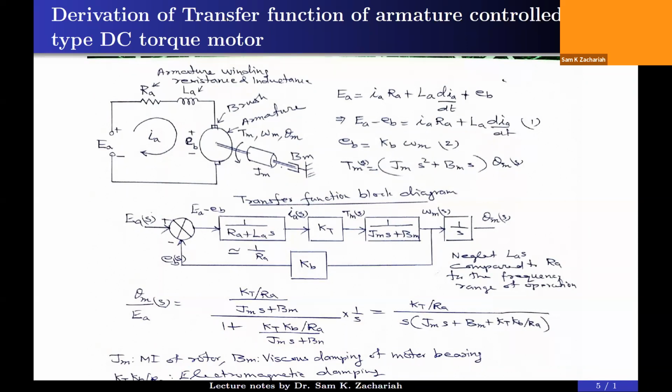But while you are riding, if the dynamo is generating voltage and the voltage is connected to the front bulb, and the bulb is producing energy in terms of heat and light, then there is a finite resistance for the circuit, and whatever additional effort you apply on the pedal with your legs, the additional mechanical energy is converted into electrical energy and some heat energy.